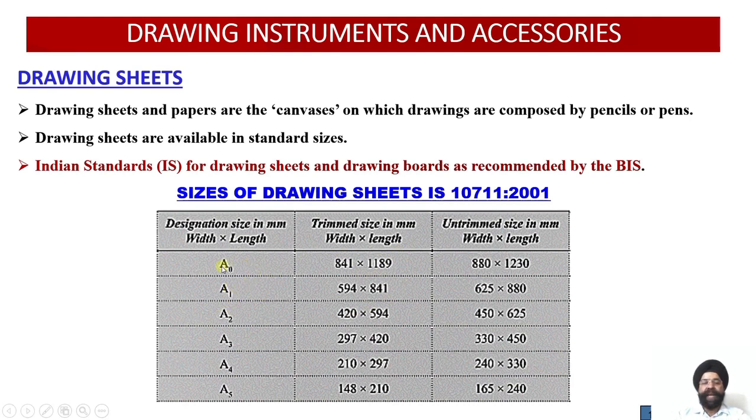If we repeat the same practice twice, we get the realization of the A1 as well as the A0 sheet, but there is one difference: if we multiply 420 by 2, in the final sheet there is a margin of 1 millimeter along the longer dimension. So 420 multiplied by 2 gives us 840, but since there is a margin of 1 millimeter, we get 841 along the longer side, whereas 594 remains the same in the case of A1.